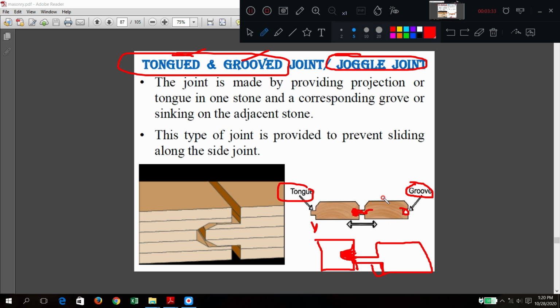Like this the stones are placed, generally for footpaths and roadside works. One side has a projection, and the other side has a cut groove. These are called tongue and groove. For this groove, the tongue of the next stone fits and is fixed using mortar.